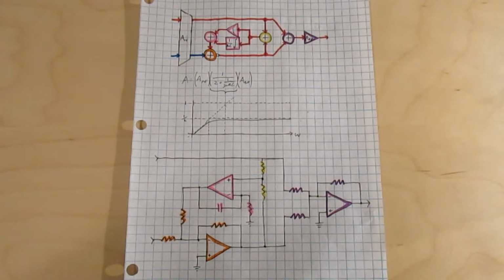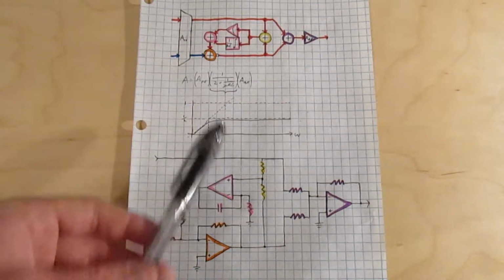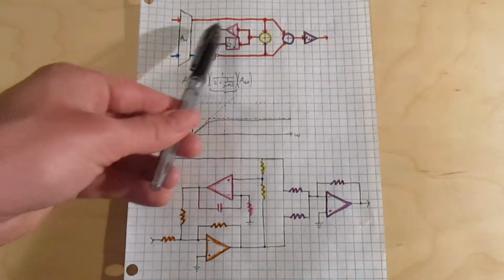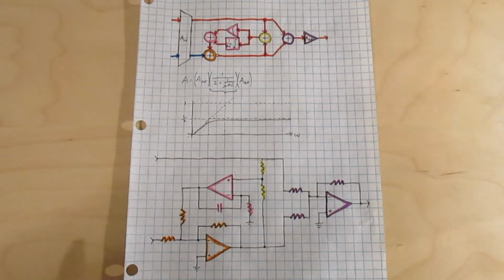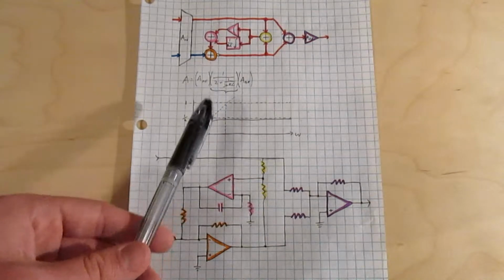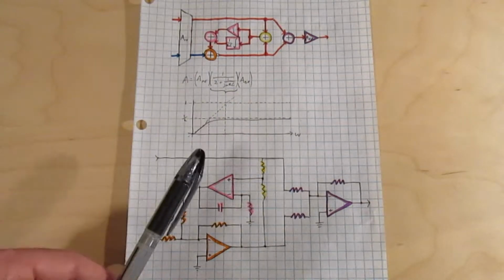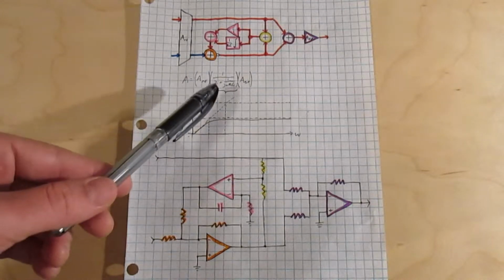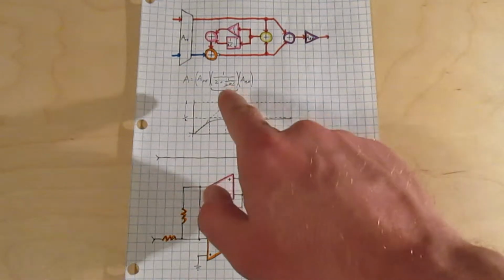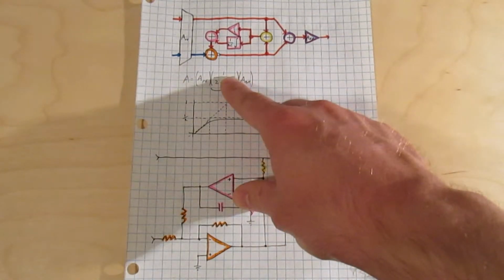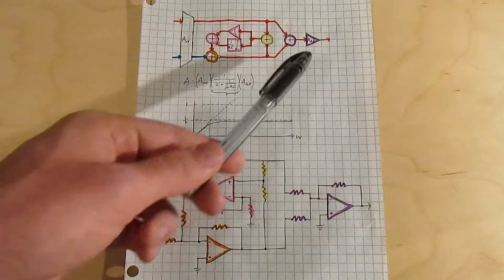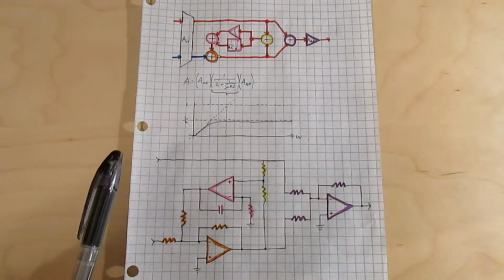So if you want to get mathematical about it, if it was just the integrator in the feedback, then the gain of the feedback path would be 1 over j omega RC. But the gain of the feedback path in Jason's circuit is 1 plus j omega RC. And when you plug that into the formula for the gain of an amplifier with negative feedback, which is A over 1 plus AB, you end up with 1 over 2 plus 1 over j omega RC. And from that you can see that at high frequencies, when this 1 over j omega RC term disappears, the gain ends up being 1/2. And that's not that big of a deal for the gain of the overall circuit, because you can increase the gain of the back end by a factor of 2 to compensate for it.